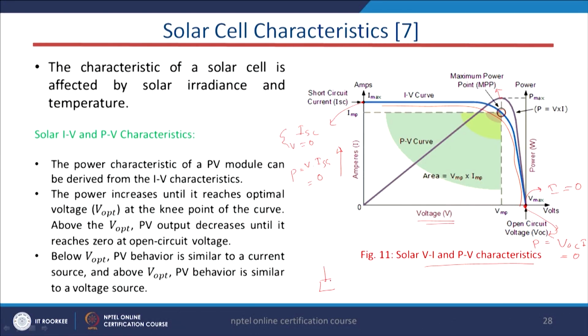If you see the previous electrical equivalent of the solar cell, let us say here we have the cell equivalent and here we have the load. Now, let us say I make this load quite large, I mean the resistance of this load tends towards infinity. Of course, it will not be infinity, it is not feasible.